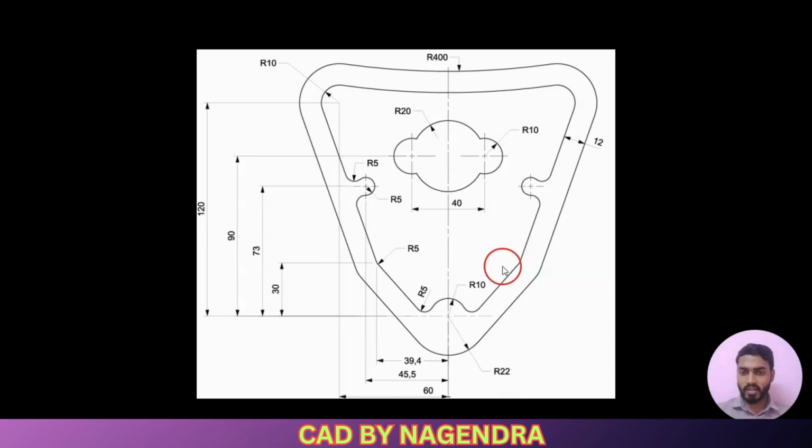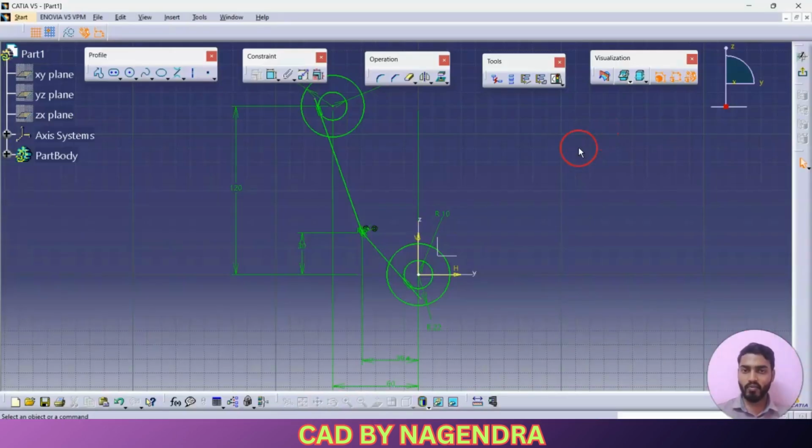Then whatever shape we have here, the same shape we need in this direction with a distance of 12. In that condition we can go with Offset. As we already know, we have different types of propagation. Now I need to make offset for all these three continuous elements with reference to tangency, so I will click on tangent propagation for this. In this direction, use Tab. As you can see at the border, we are going to jump into offset. So the dimension we need here is 12. Let's say Enter.